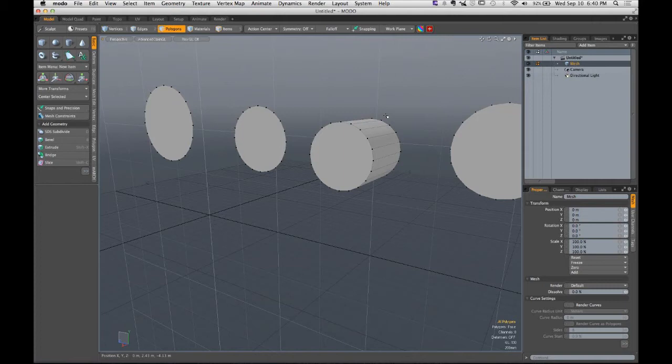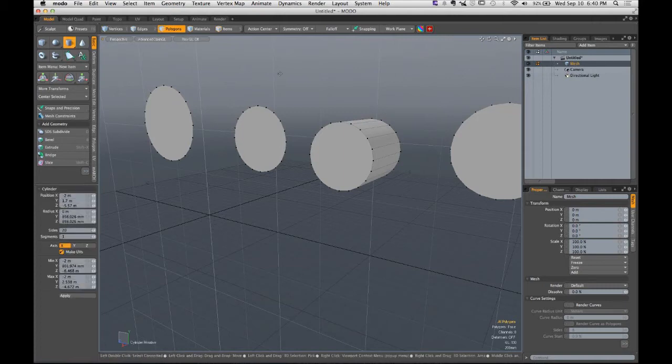Absolutely. Let's do it one more time. So step numero uno. After we turn on the cylinder tool, just single left click in the OpenGL viewport. Step number 2, move your cursor away from the tool handles and make it some distance. Step 3, hold the control key. Step 4, left click and drag. And you'll generate a perfect circle every single time.